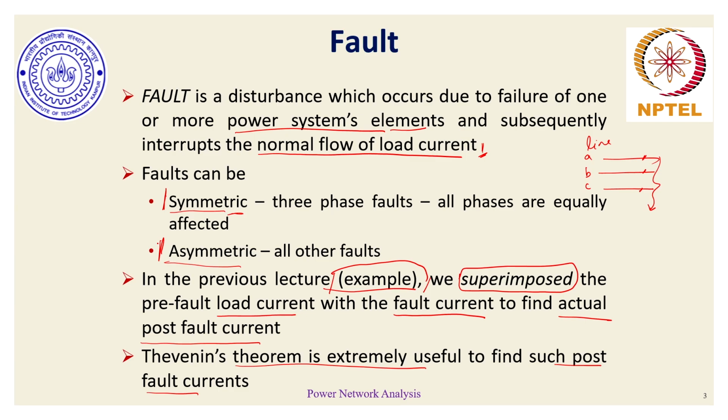Thevenin's theorem indicates that, given an electrical network with sources of the same frequency, an equivalent network can be created for this actual network with several sources and loads operating at the same frequency, reduced to a simpler source and load combination, where the source is called the Thevenin source and the corresponding impedance that appears across the 2 points of interest is called the Thevenin's impedance.